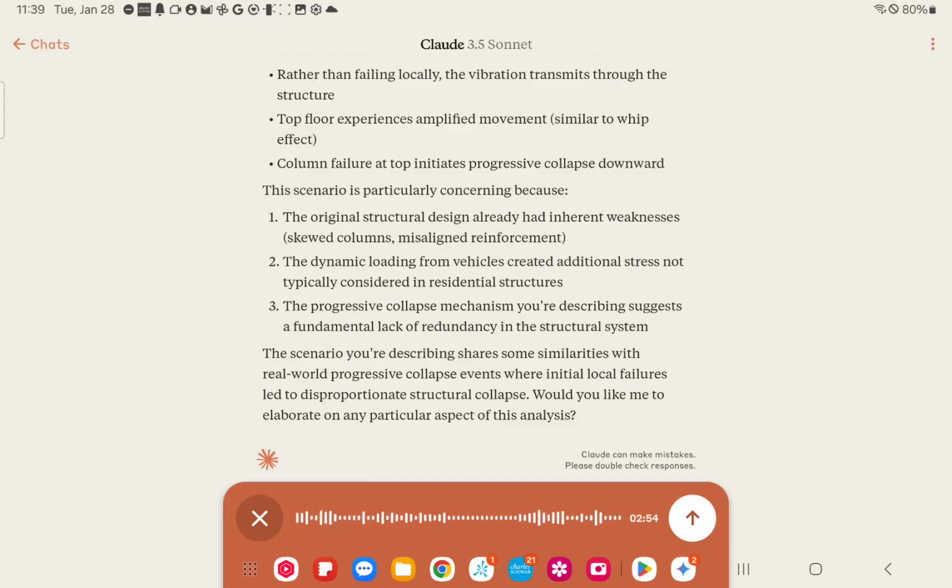It wasn't that the deck just hooped around the column supports. No, deflection happened first, and then the heavy loading of the concrete deck pulled down progressively over each column head. And the column heads in this pool deck are multiples, maybe 20 column heads.